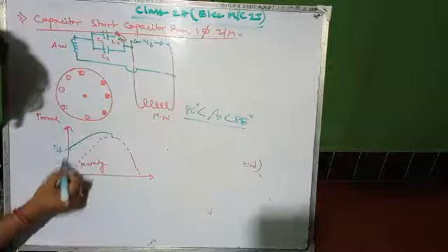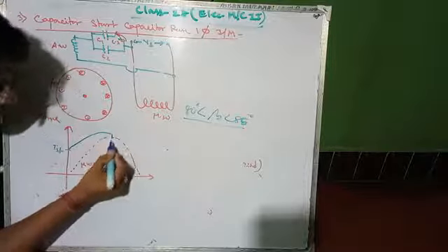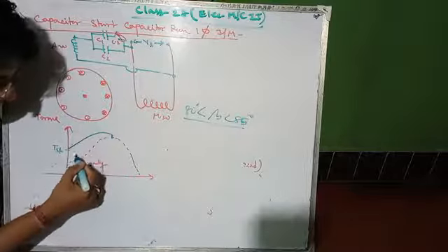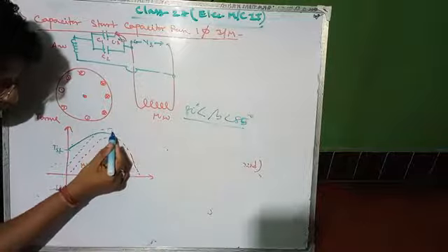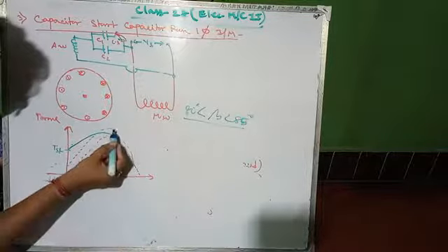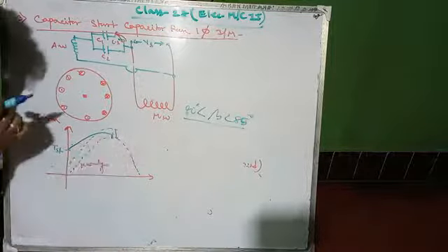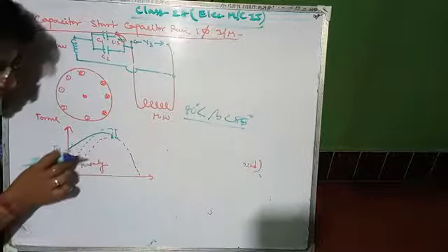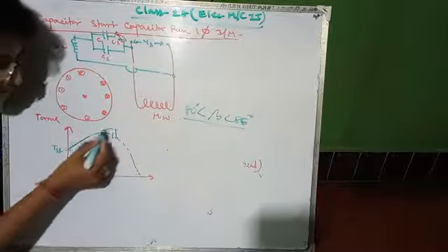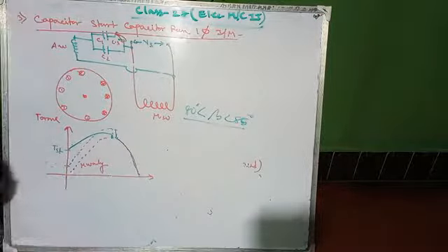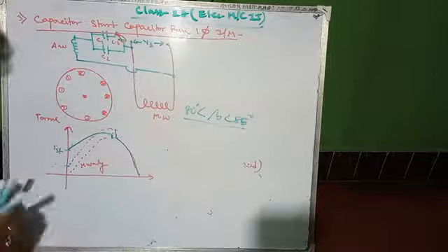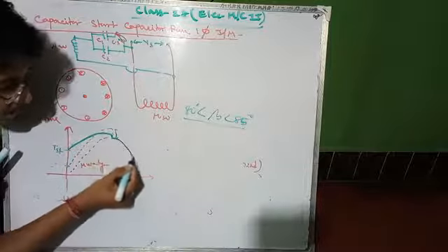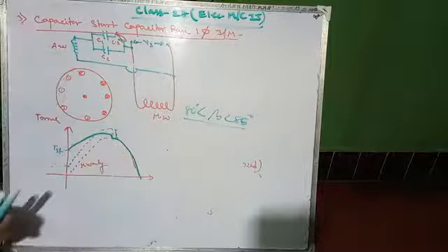The starting torque is enhanced and the switching is less steep. Previously, with only the capacitor split phase, the steepness was larger and the starting torque was less. Now it will follow this path: the starting torque will be higher and the switching is less steep.